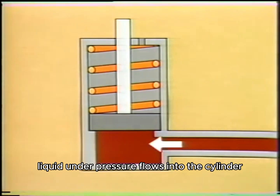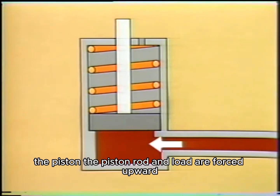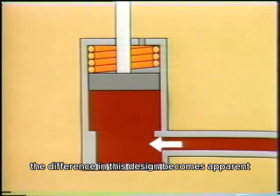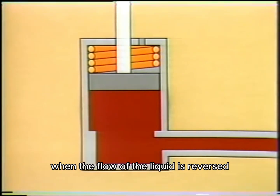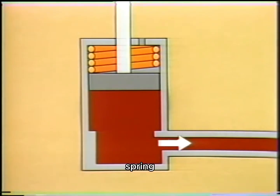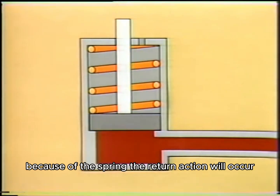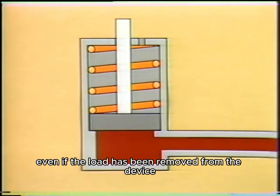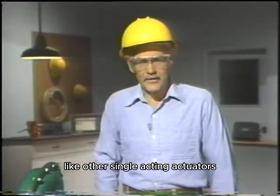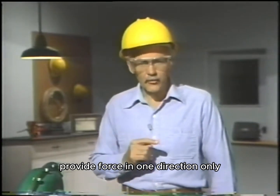Liquid under pressure flows into the cylinder. The piston rod and load are forced upward, compressing the spring. The difference in this design becomes apparent when the flow of the liquid is reversed. As the liquid flows out of the cylinder, spring tension returns the piston to its original position. Because of the spring, the return action will occur even if the load has been removed from the device. Like other single-acting actuators, the hydraulic actuators we've just seen provide force in one direction only.